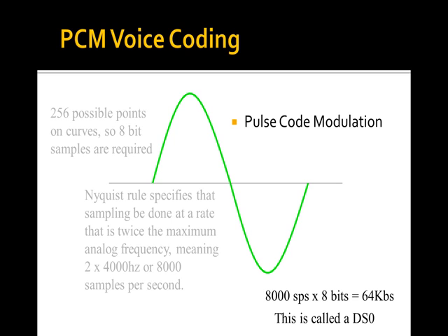Okay? In the analog days, we did all of this with filtering. Because filters don't work perfectly, you can't say, I want 300 hertz to be the cutoff, and 299 hertz doesn't get through and 300 hertz does. We can do that with digital techniques. You can't do it in analog techniques, which is how all this stuff was built. So we actually built the filters a little wider than we needed them to be. We let the filters pass 0 hertz through 4,000 hertz. So here's a 4 kilohertz channel with this 3 kilohertz signal in the middle of it. Okay? The extra bandwidth is called guard band.